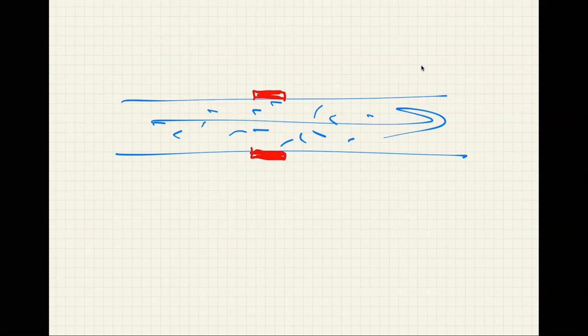So you need to monitor structural health of this pipe. What do you do? You put piezoelectric elements there, and with ultrasound waves, you can see whether there are changes in a material, whether there are developments of the cracks.